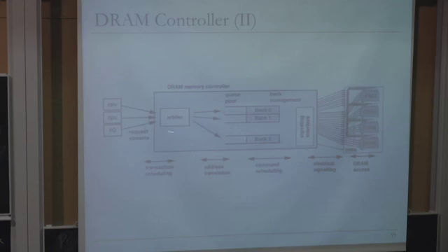If you have multiple ports, you can assign them right away here into the banks. But you also have request buffer queues. This is one example that can buffer the requests for each bank. Again, you could think of a centralized queue as well for all banks, right? Again, dynamic versus static partitioning. In this case, I show you queues for each bank. And you have a scheduler here that picks which request should be scheduled next.